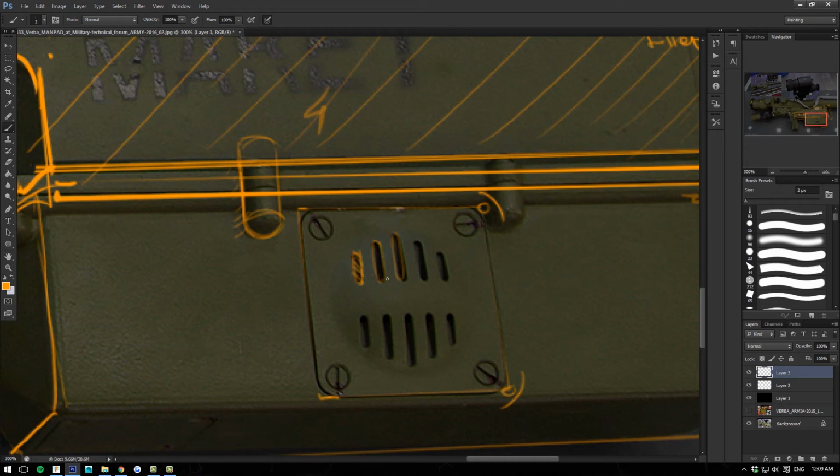And then once it turns into a face, there is a very useful tool for this kind of shape. This tool is called a slot, but it can also be achieved from a rectangle with filleted edges. In reality, if you're trying to save time or trying to be very precise, which is the right way to go, you can see that there's an axis of symmetry here, which there's actually two.